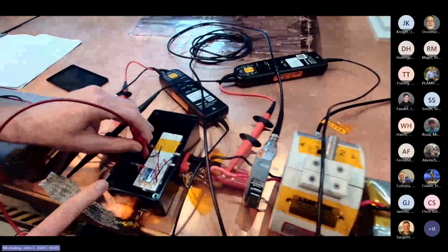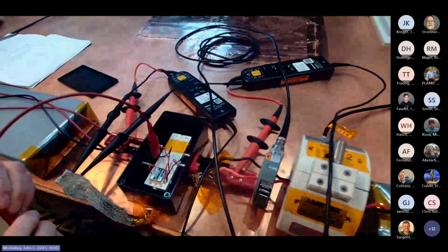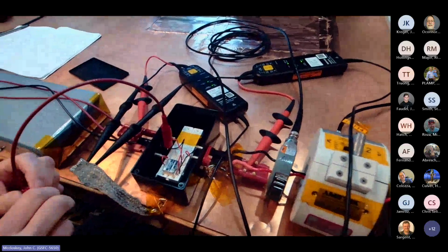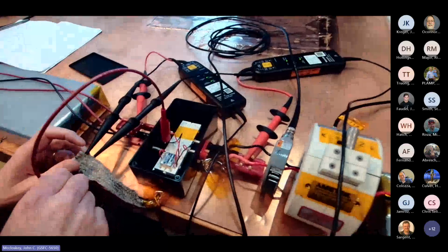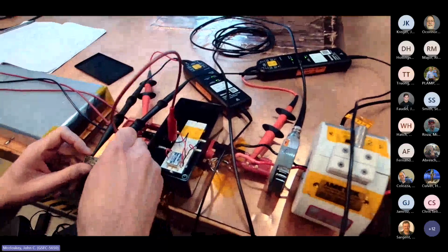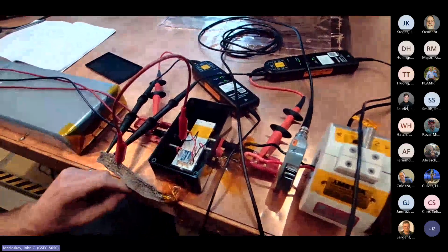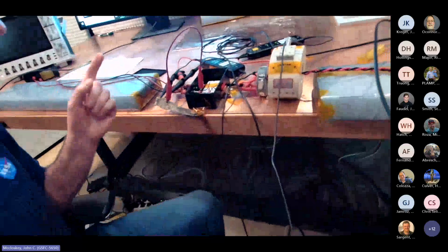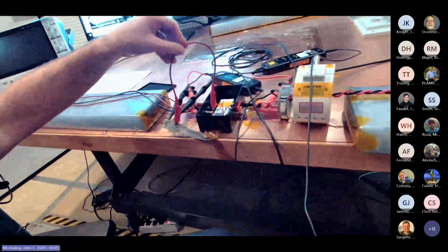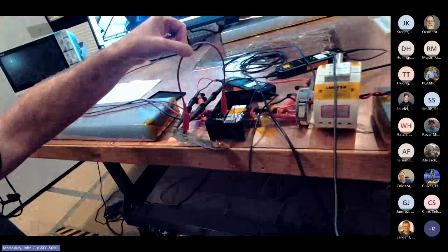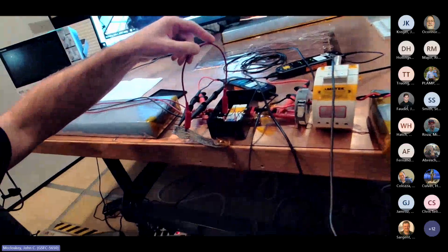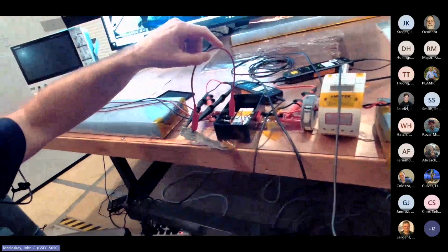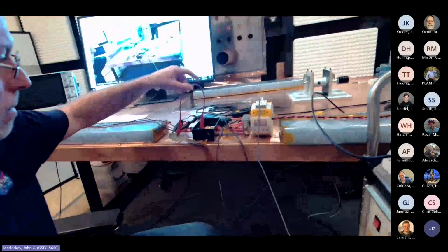I'm not trying to defuse a bomb, so it's less crucial. Would you always cut the green one? I don't know. But going from the black wire to the braid. So now I'm tying the output reference to chassis, which is generally what we do. Now it's a very bad connection. I've connected an antenna, but at least from a DC standpoint, now the output is referenced to the chassis.